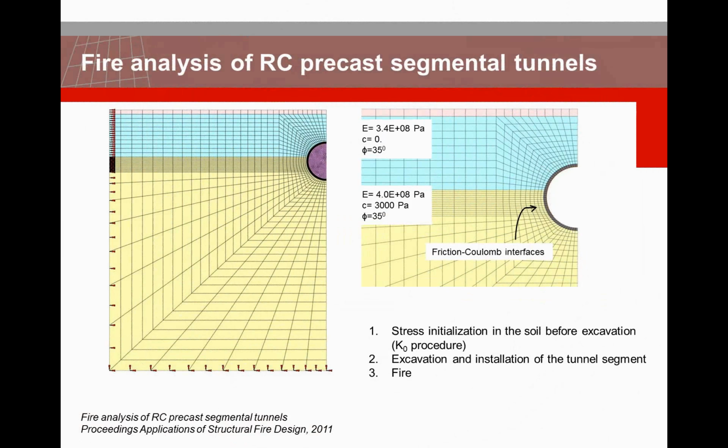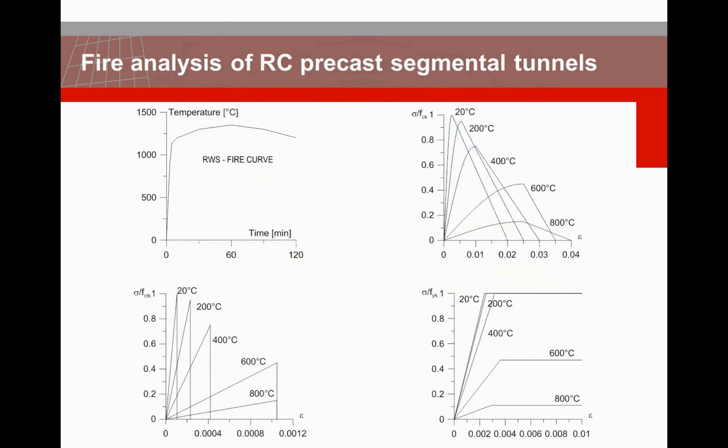This could be a steel grid or could be fiber reinforcement. So depending on the type of material that you're going to use here, you can characterize that based on the effect of fire on them, so material degradation, the induced level of the fire, and how the material is going to lose their strength.